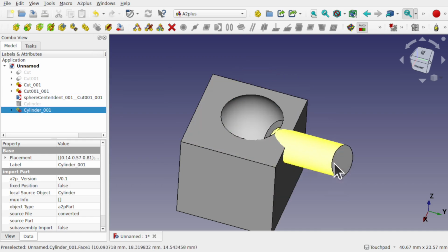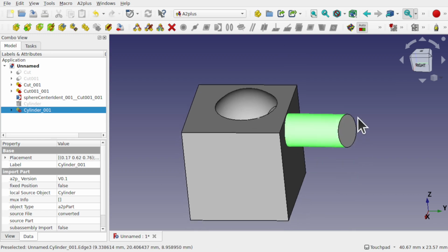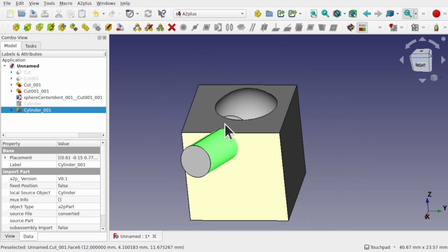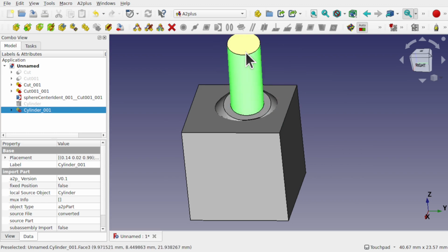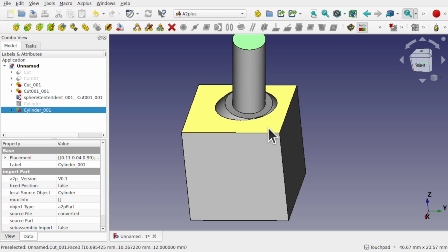Remember that the solver doesn't allow for collision detection, so just be wary of that. It's a dynamic assembly, but we haven't got that kind of collision detection in there to stop it from passing out of this circle. There's certain things we can do to simulate it up to an extent, but that requires additional constraints, and the more constraints we have, obviously the more processor power intensive it is. But this is enough for a basic ball joint. So that's the sphere in sphere constraint.